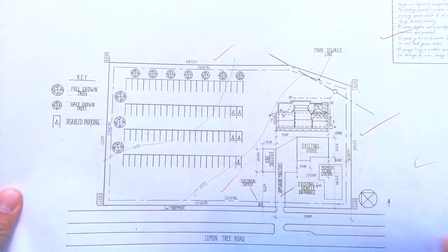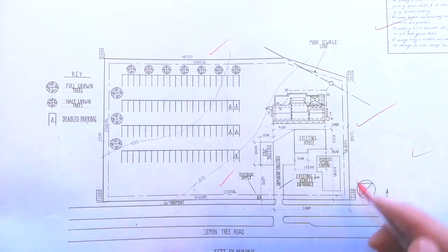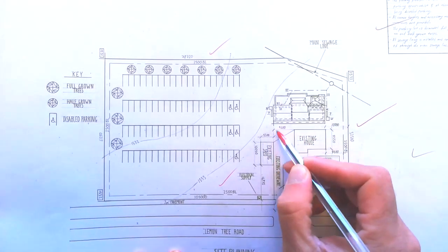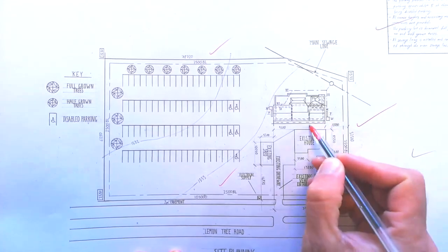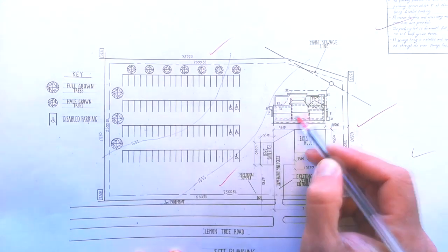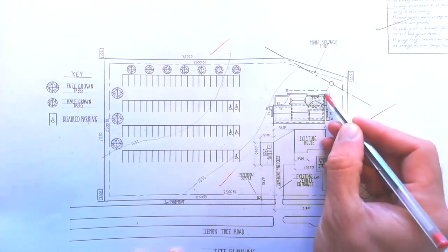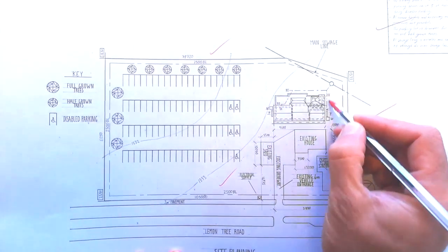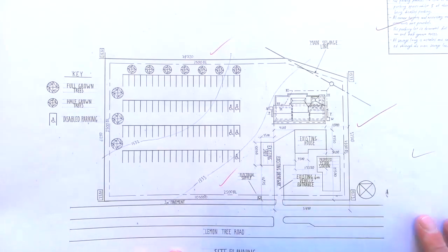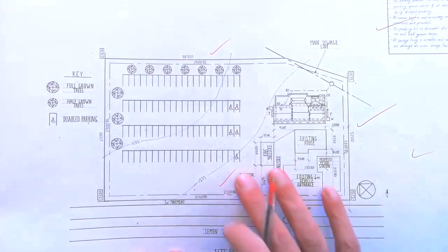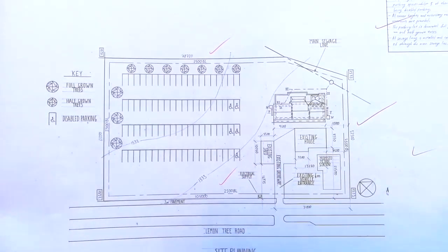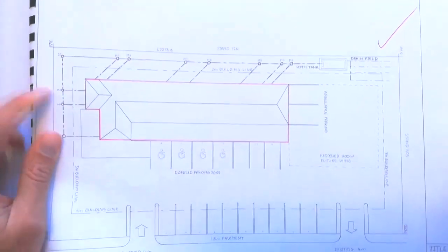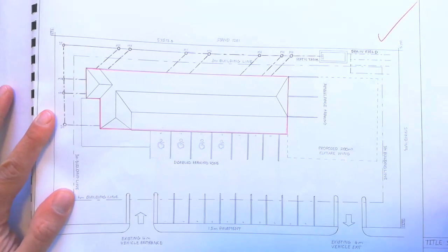Okay, here's a similar site plan, and you can see here there's a bit more to it, a couple of setting out measurements. So it's possible for us to determine here the position of this new building, although what's missing here is the highlighted red and the brown for your sewer lines, but it's quite clear and understandable for someone wanting to build this. Okay, and our last example of a site plan is this one here.